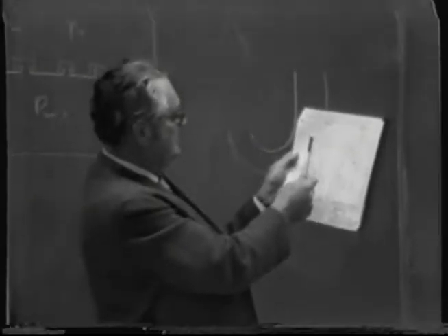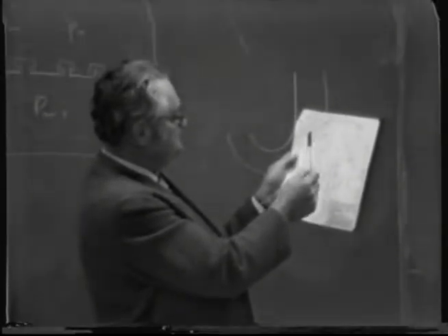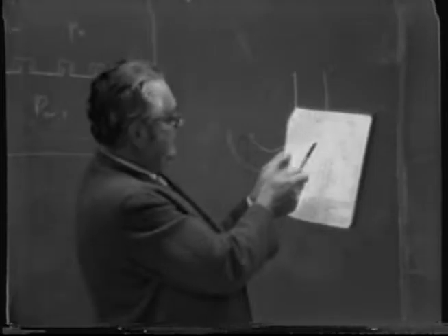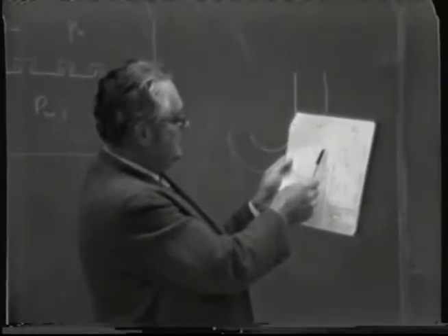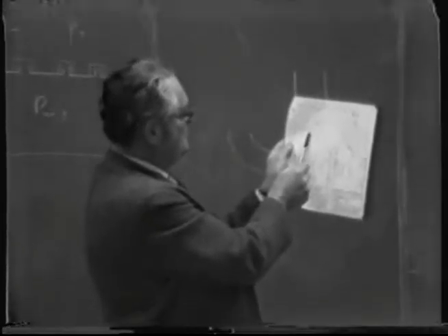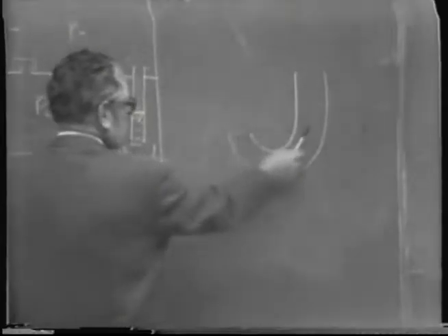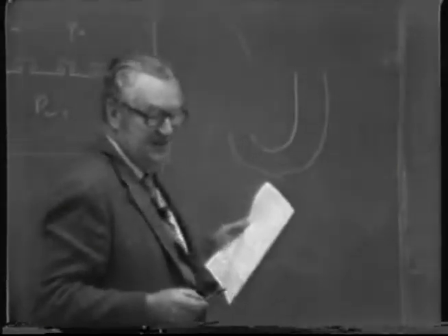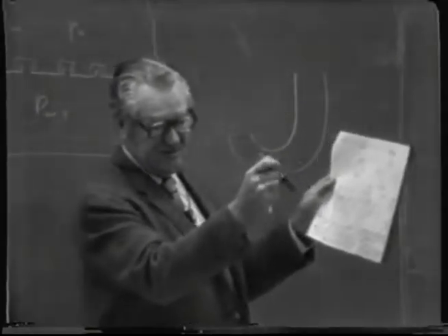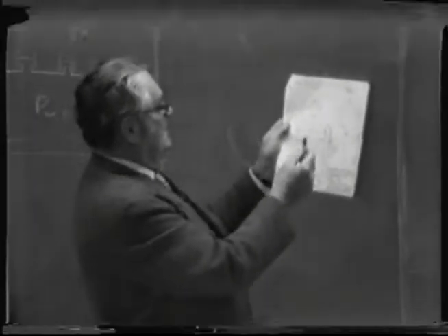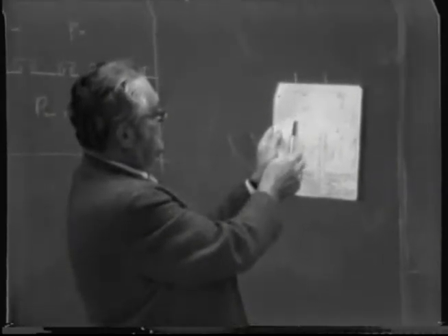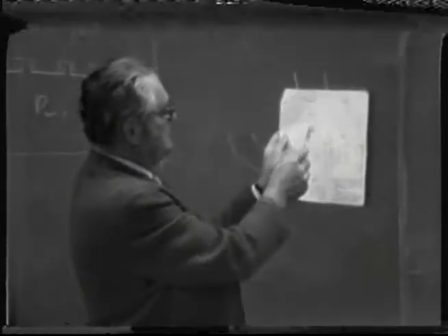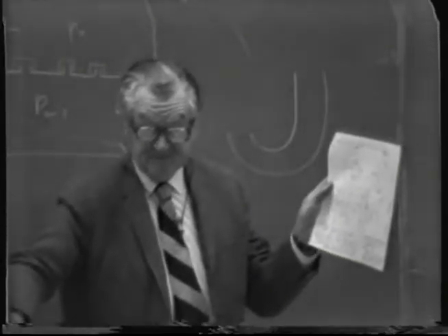Now look here on the left in the upper one, you see they had two J-type downcomers, and the double circle represents a J downcomer. It doesn't represent two downcomers, but one J tube. So if these represent the discharge points, then the single circles represent the overflow to the tray below.